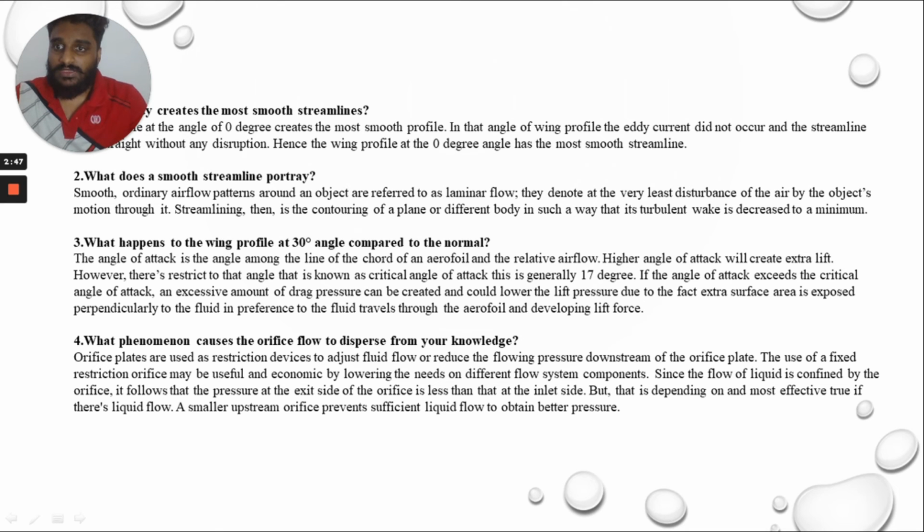The angle of attack is the angle between the line of the chord of an aerofoil and the relative airflow. A higher angle of attack will create extra lift. However, there is a limit to that angle, known as the critical angle of attack, which is generally 17 degrees. If the angle of attack exceeds the critical angle of attack, an excessive amount of drag force can be created and could lower the lift force, because extra surface area is exposed perpendicularly to the fluid instead of the fluid traveling through the aerofoil and developing lift force.